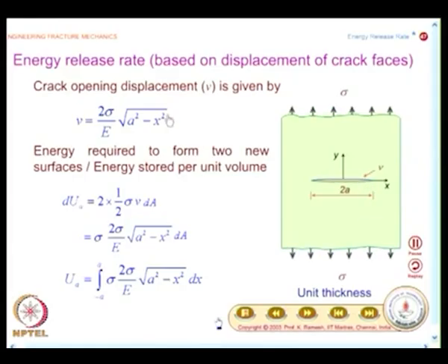That is the reason why I said in the class that when you have a single crack, extend it by a little and close it; that is the best way to identify the interrelationship between K and G. Finding the energy release using crack face displacement was only a historical note.